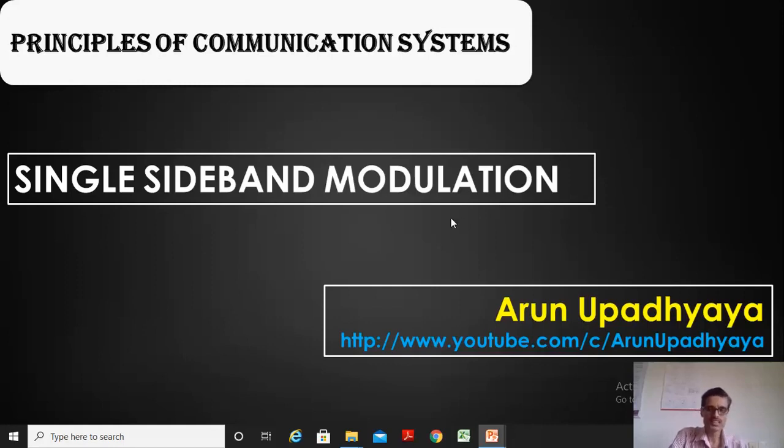Now, since both sidebands carry the same information, we can suppress one of the sidebands, maybe the upper sideband or maybe the lower sideband, and transmit the signal to the receiver and convey whatever information you want to convey. That means you transmit only one sideband, or single sideband. Such a method is called single sideband modulation. The advantage of this method is we save a lot of power as well as bandwidth, because the bandwidth required to transmit an SSB signal is just W Hz, half of double sideband suppressed carrier and double sideband full carrier.